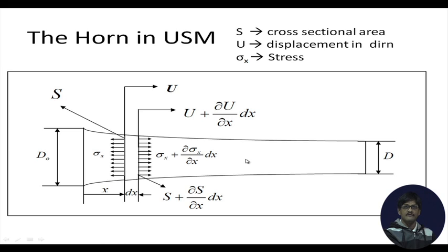At the node points we have no motion, and at the antinodes we have maximum motion. So, first question, where would we like the antinodes to be? The antinode should be at the connection point between the transducer and the horn, and ideally we would like the position of the cutting tool to be an antinode point as well, so that it will be vibrating with the maximum amplitude. At some point in between, we will definitely have at least one node point which has no displacement, and at that point we can hold this horn, because physically we have to hold it at some point.